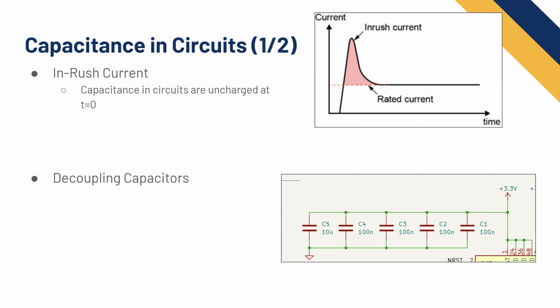The reason that I have this is because the microcontroller is pulling power, and it's usually digital logic, so it's going to be very jumpy. And so these capacitors allow, like you said before, when there's a lot of changes in the voltage, the capacitor can absorb some of that and source some of that. It goes back to basically the filters we were talking about before. You have some resistance in your circuit, then you have the capacitance.